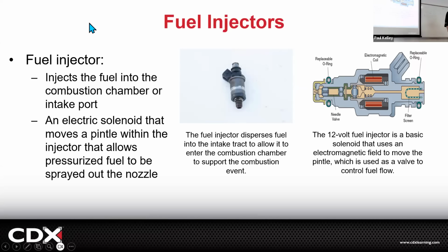So if we had an injector that had the harness cut to it, what's that injector going to do? It's going to be seated. So is there going to be any fuel spray? No. So if that injector is not getting 12 volts and ground, it doesn't spray any fuel.